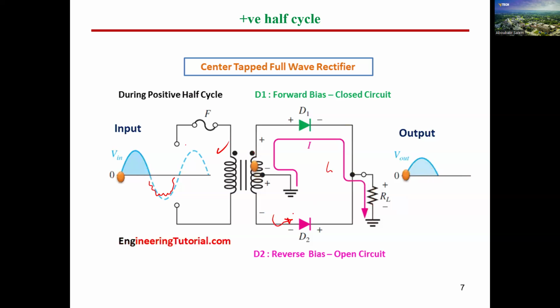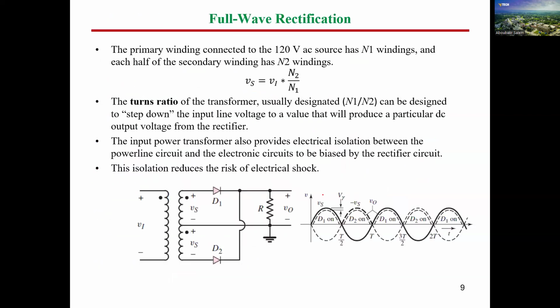And if the diode D2 is conducting in the next half, it's going to connect the positive to the top level again, or to the output resistance again, which means now all of the time the output is going to be positive. So this is the waveform now. Can you see here, guys?